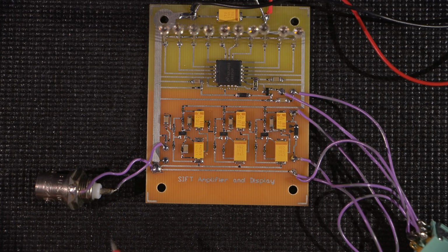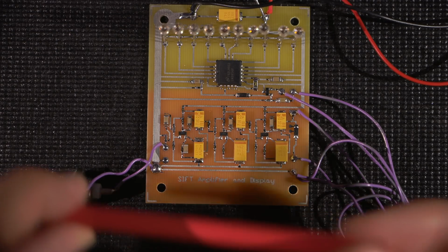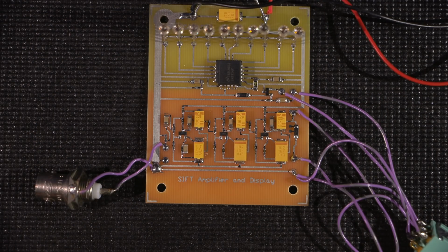Put your oscilloscope on AC coupling. You want the input of your scope AC coupled, not DC, because if you encounter any DC voltage here, it's going to lift that signal possibly off the screen and make things confusing. So for troubleshooting, if you're not looking for a DC level, AC coupling is always very, very important. So AC couple your scope. You'll find that in the menu, and sometimes it's just a switch on the outside.